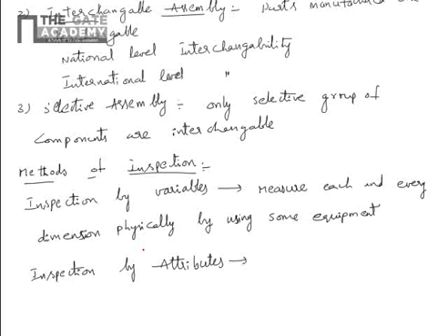The dimension is not measured, but the decision of accepted or rejected is based on the entry of the gauges. Limit gauges are used to inspect a component.